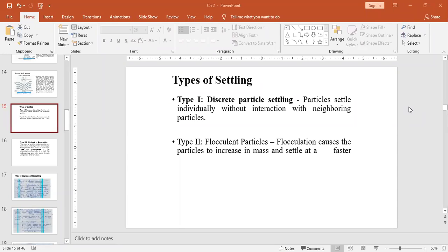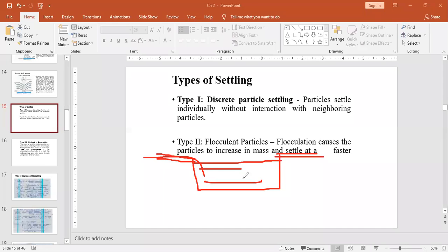That means without using any kind of chemical, we are allowing the particles to settle down at the bottom. Suppose this is a tank, and here we have provided the inlet and here the outlet. When water is coming through this channel, it will fall down, and you can assume this is completely filled. When it passes towards the end, because this is a channel with small area, and here in this tank, this is a section you can say.